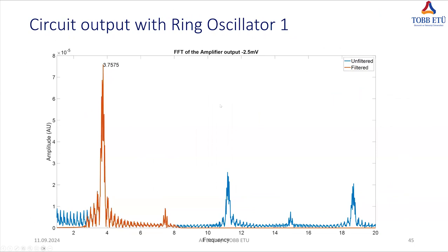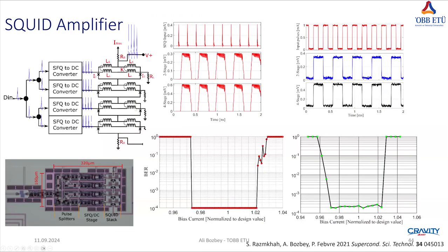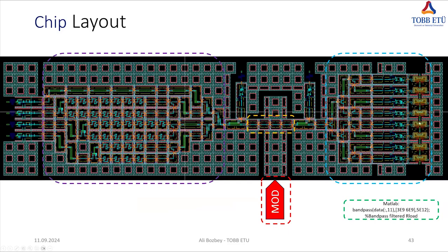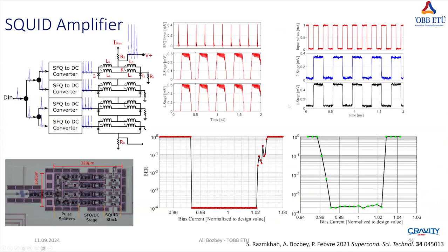But this circuit is not enough because everything is superconducting here, including the Josephson junction. So the impedances are very low. The output impedance of this circuit is just 2-3 ohms. So when you directly connect it to qubits, which are generally designed to match 50 ohms, most of the signal will be reflected.